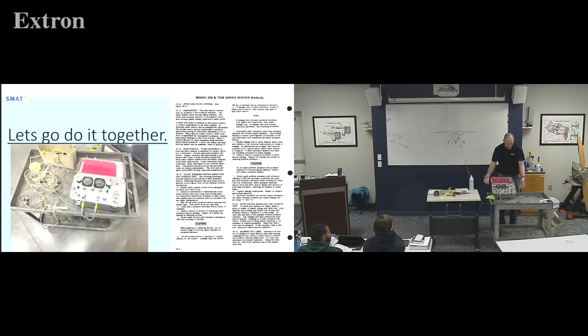So if I'm on the vacuum side, let's say, well, we'll go to the pressure side. We'll say we're doing our pitot first. As long as this valve is closed, and I just have this capped, I could hook up shop air to that or nitrogen. Same thing here, I can hook a vacuum pump, but I'm going to pump it up. If you were by me, you would see my little pressure dials going up. I'm filling up the little canister in here.